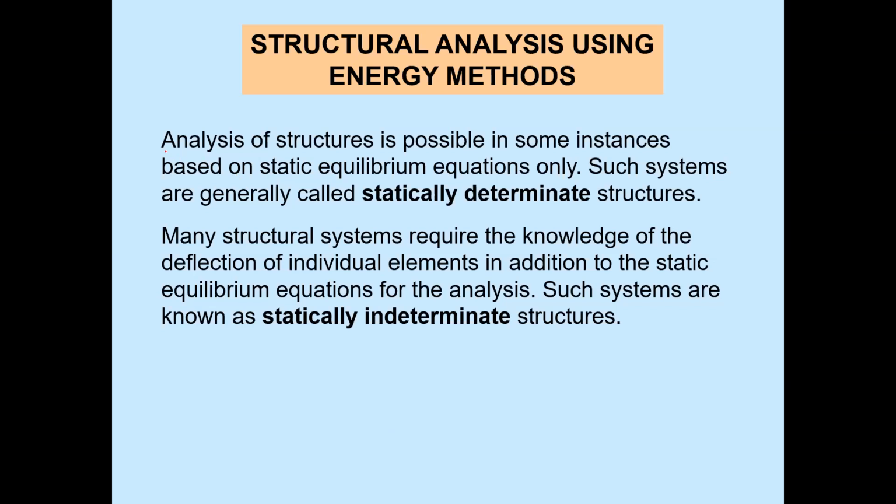So analysis of a structure is possible in some instances based on static equilibrium equations only. Such systems are generally called statically determinate structures. So what it means is that if we can solve the equations of a structure by just static equilibrium equations, then the structure is known as a statically determinate structure.